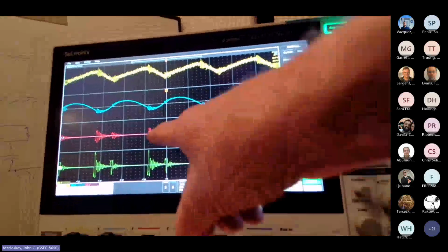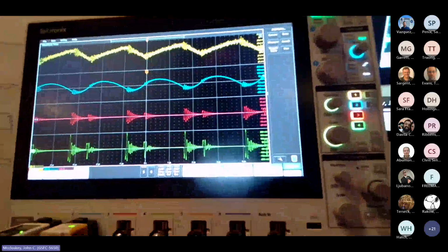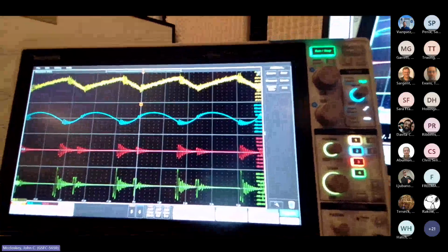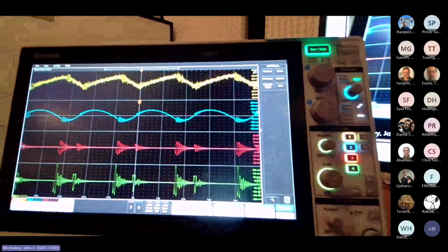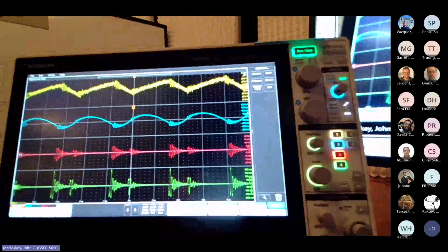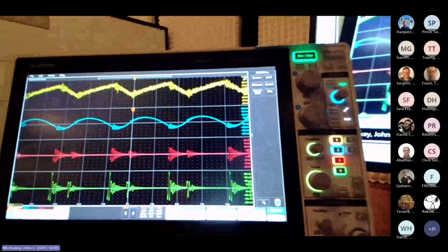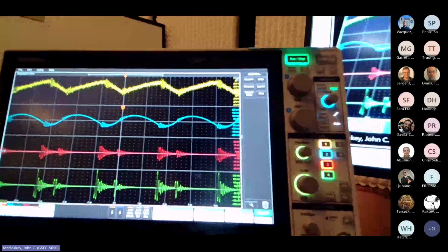And every now and then, this junk was landing on a clock edge, and we believe was causing spurious clock transitions, but only very occasionally, right? It was a very intermittent problem, but that really helped us explain most likely what we were seeing.